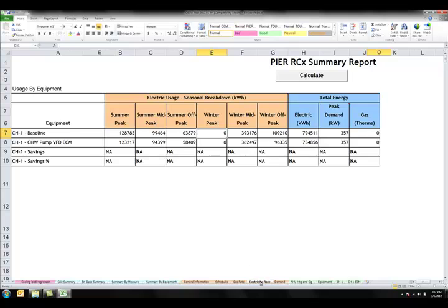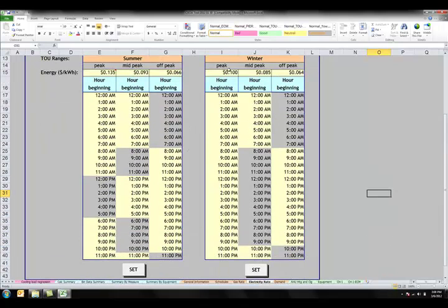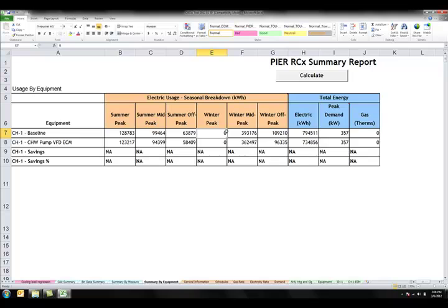Let's take a look at that electricity rate worksheet. You can see there's no hours in the winter peak period. That's why that's 0. You can see the utility rates tutorial for a discussion on time of use periods. For buildings with Saturday or Sunday operation, you'll need to run the tool twice because the gas and electric utility schedules assume that all days are the same, while most utility tariffs use off-peak rates for all hours of the weekends.